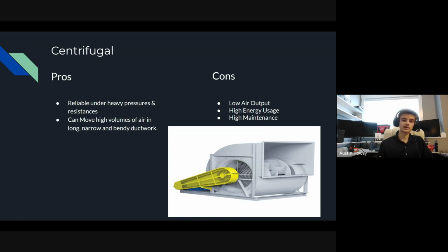they create a lot of static pressure. So you can suck up wood and metal shavings with these, but you have to output a ton of power to get just a little bit of air moved, and that's why these are usually in much narrower ducts.